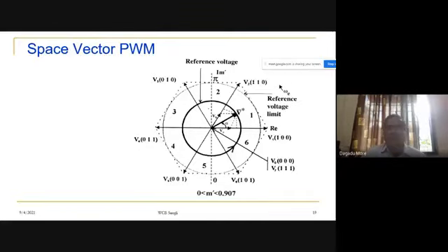So this is our dotted hexagon that you are seeing. This is the V1 space vector, and V2 is also there. There are 6 space vectors for the switching states of the inverter; we have 6 active vectors and 2 inactive vectors. What is the magnitude of V1? Anybody? The magnitude of V1 is VDC.